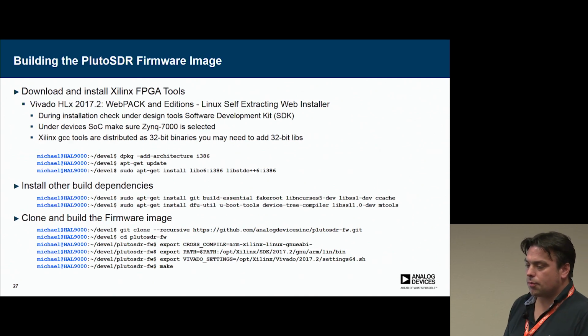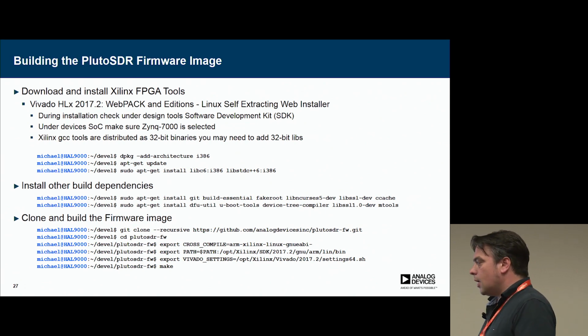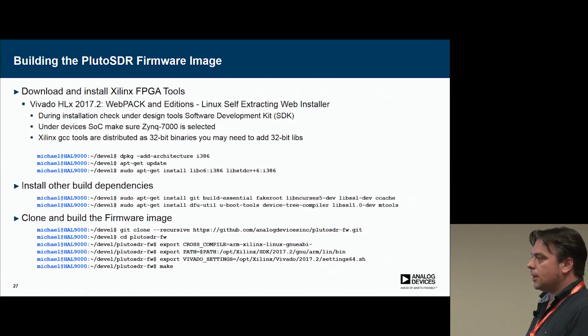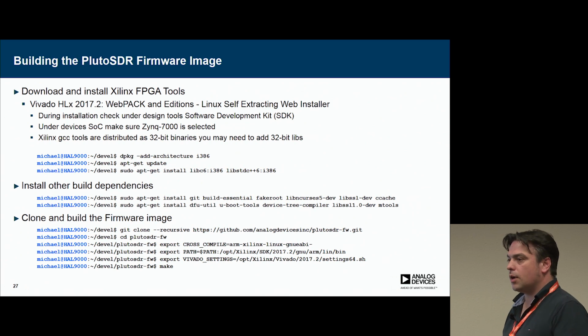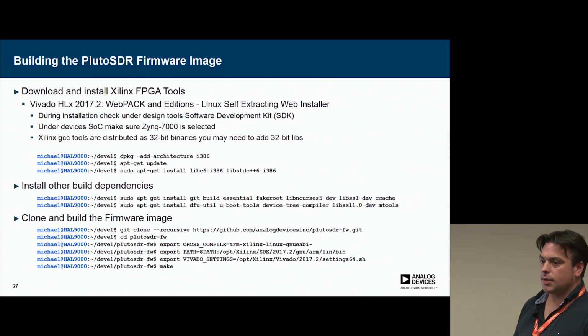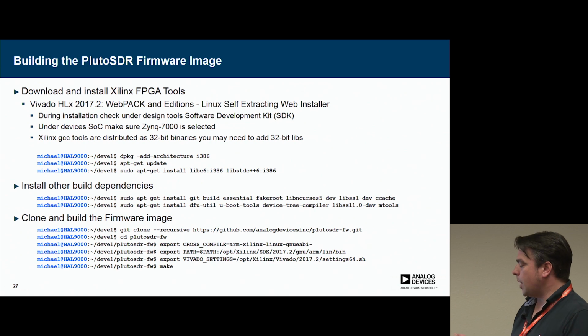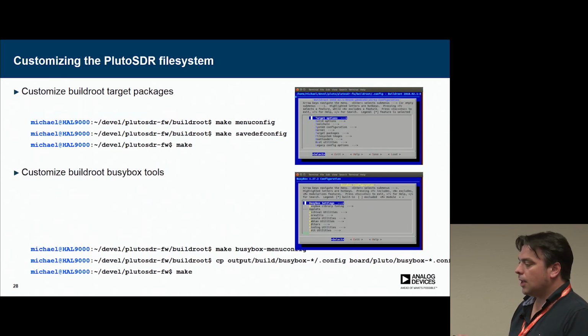The Pluto has a firmware, and everything is open source. And that's just a small recipe for how you build the PlutoSDR firmware image. You install some build dependencies, clone a repository, set up some environment variables, and then type make. That's how easy it is.